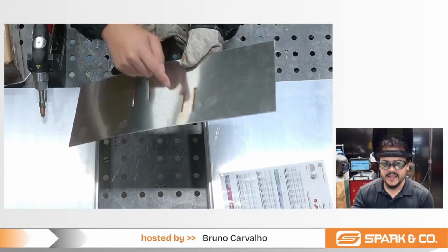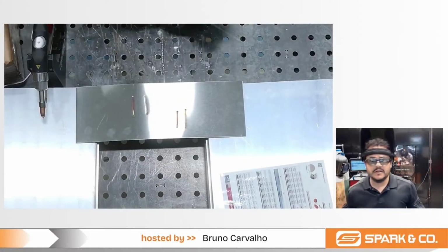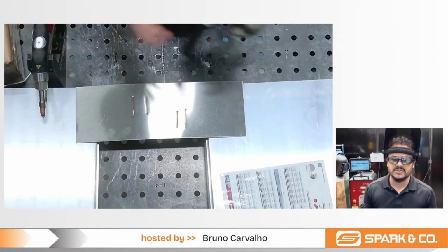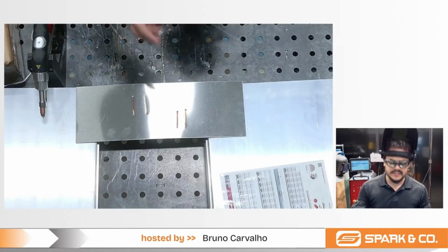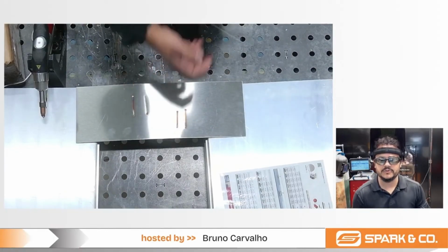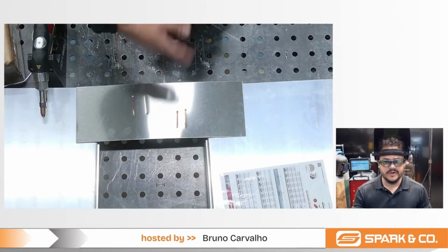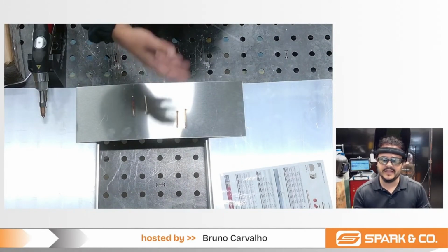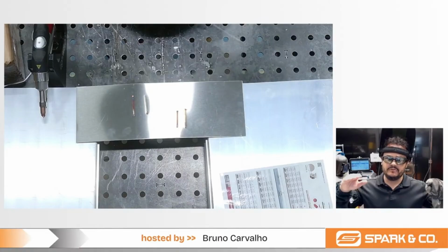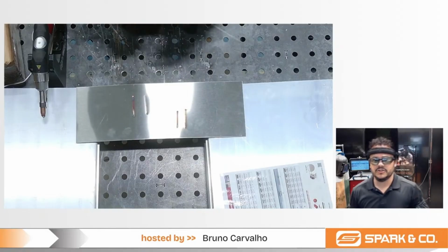We don't want that. Then you can argue, well, if I don't want that, I can just lower the power. If you're welding with 500 watts, just change it to 400. The thing is, yes, in this case 400 watts will not be enough for the laser to pass through the welding toes, but you are losing penetration where you have the wire, or if you're just fusion, you're gonna have a lack of penetration in the middle. So you want to equalize that, to have an equal penetration all the way. That's why power compensation is so important.